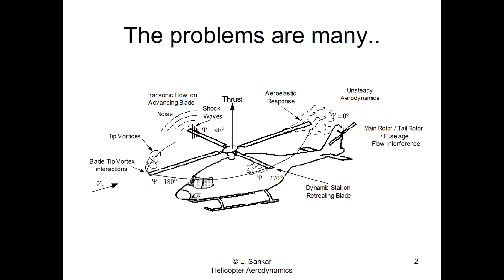Remember, all those links are exposed to the air in many cases. Round circular rods, including the hub, have a lot of drag. An aerofoil has a CD, drag coefficient, of 0.01. A circular cylinder has a CD of 1, almost 100 times higher. So the small hub region of a rotor that we see in this picture can dramatically increase the drag.